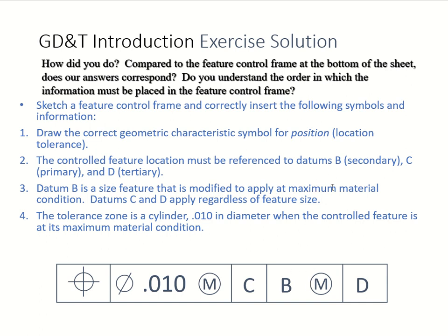Set it so here, B with the max. So therefore, I just read B with the max. I don't even read any of that, to make it faster. So B. And then your C doesn't have it, so regardless of feature, bang, bang. I'm following the standard and I don't need to put the circle S in there with it. Some students want to put it, that's okay too.